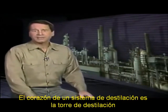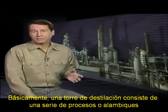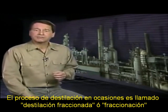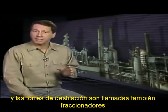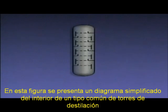At the heart of a distillation system is the distillation tower. Basically, a distillation tower is a series of distillation processes, or stills, stacked on top of each other. The process of distillation is sometimes referred to as fractional distillation or fractionation, and distillation towers are sometimes called fractionators. Fractionation is distillation that occurs at different levels in a tower. This is a simplified illustration of the inside of one type of distillation tower.